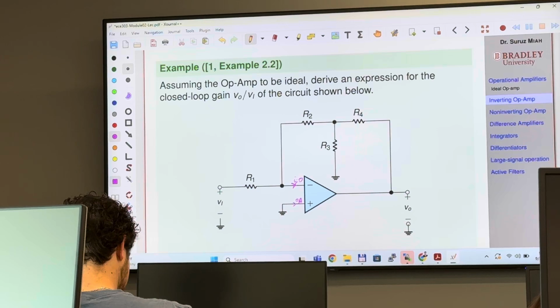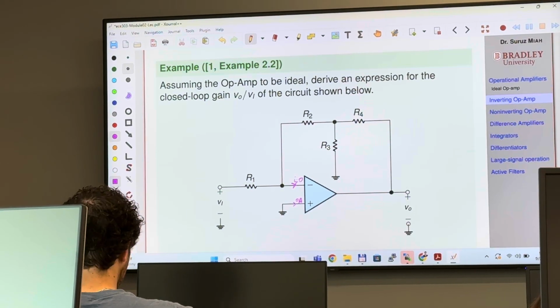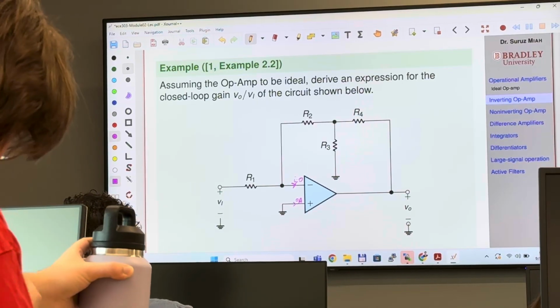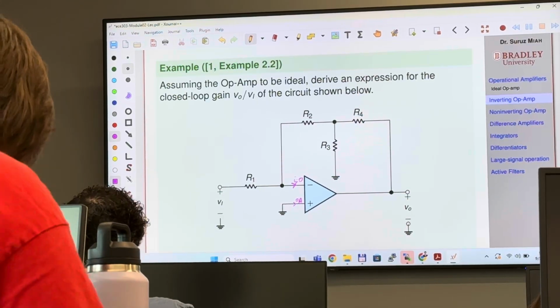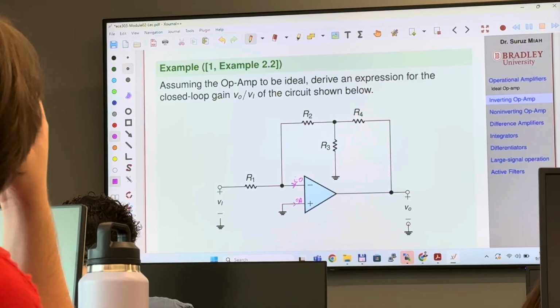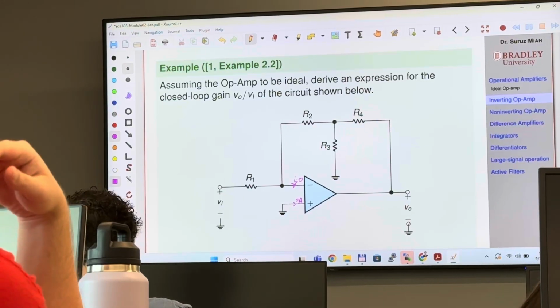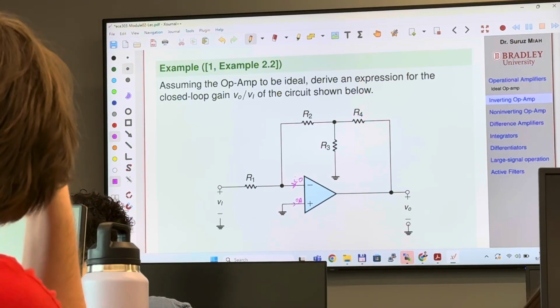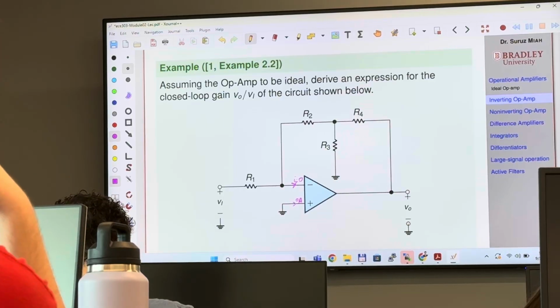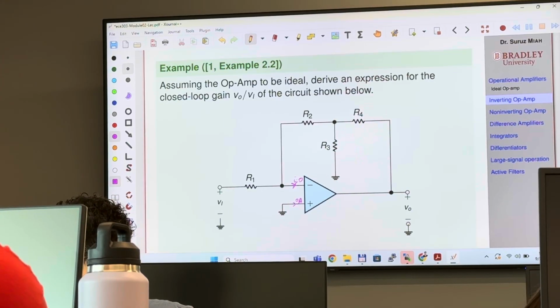What is the unit of inductance? And capacitance? So make sure, when you have inductive reactance, it has the unit ohm, but many people get this confused, so they write the unit Henry. Unit of reactance is Henry? No, the unit of reactance is ohm. Unit of impedance is ohm.